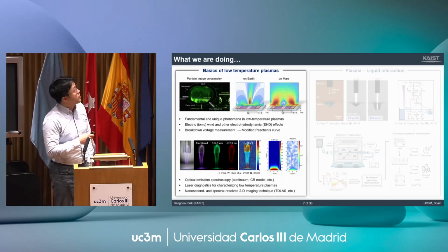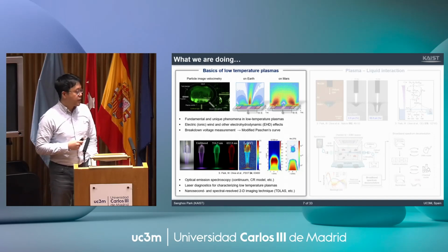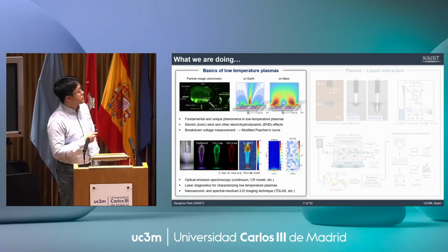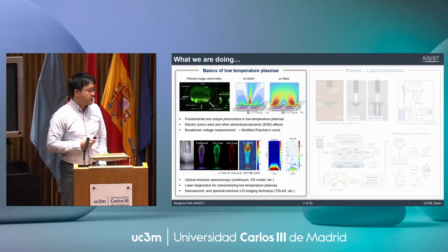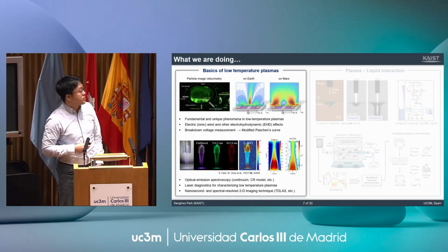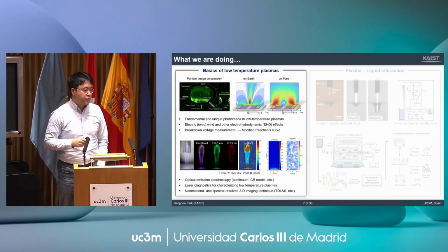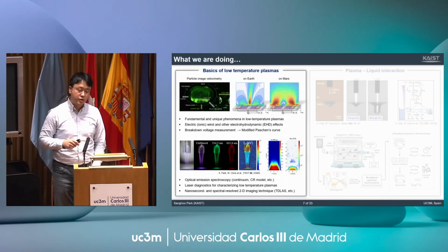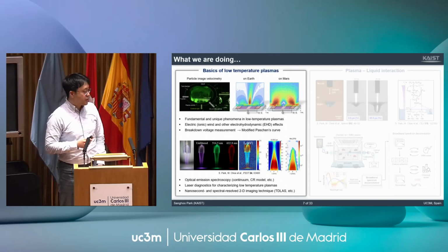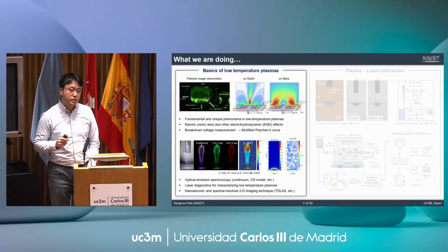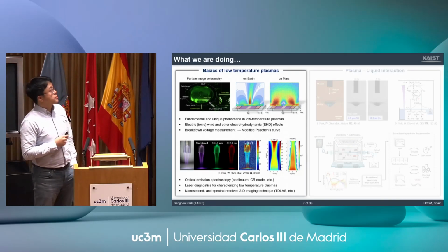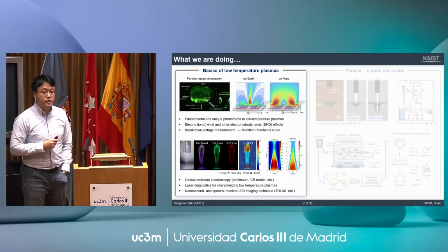So, for example, we are measuring some ionic wind produced on the surface due to the plasma by building this kind of laser diagnostics. With this particle image velocimetry, we can visualize the flow structure produced by the dielectric barrier discharge. More recently, we are studying the difference between Earth condition and Mars condition. We are wondering how this flow structure can be changed in the Mars environment.